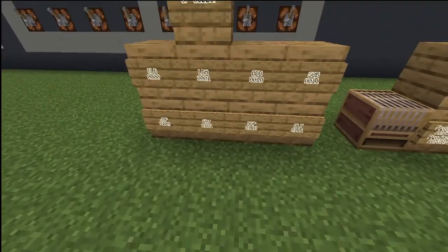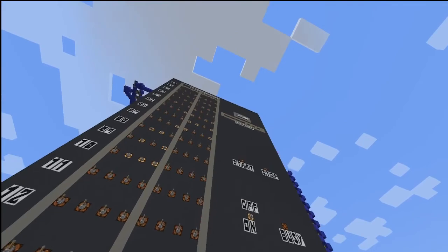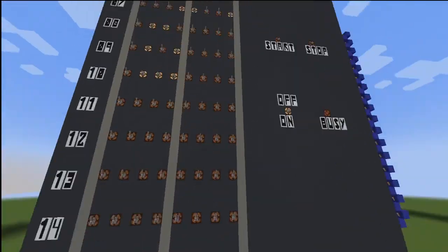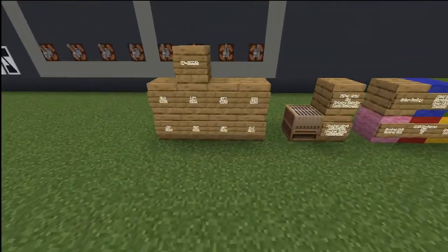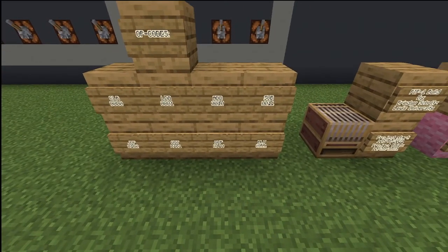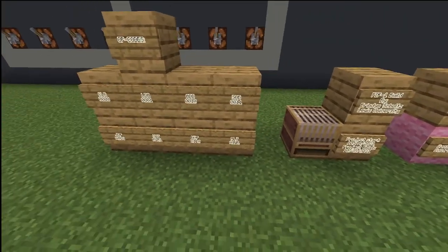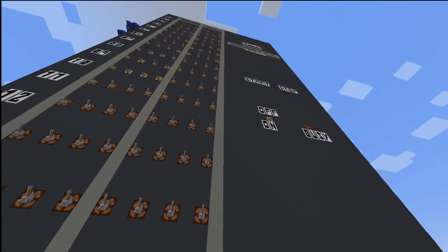There's out, which will take whatever's in the A register, move it to the C register, and the C register is directly linked with the readout, so that'll be your output. I also have a NOP, which is no operation. It just lets a clock cycle pass. It doesn't do anything. And then you have a halt, which turns off the clock and ends the program from running.